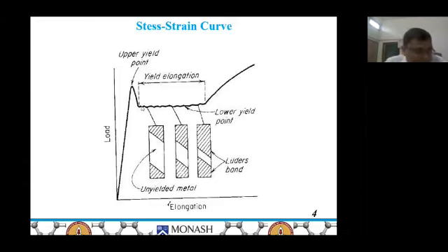At the upper yield point, a discrete band of deformed metal, often readily visible with the eye, appears at a stress concentration such as a fillet, and coincident with the formation of the band, the load drops to the lower yield point. The band then propagates along the length of the specimen, causing the yield point elongation.